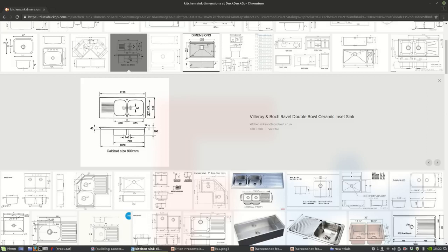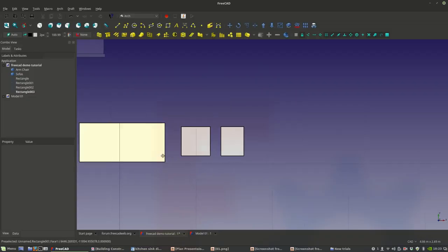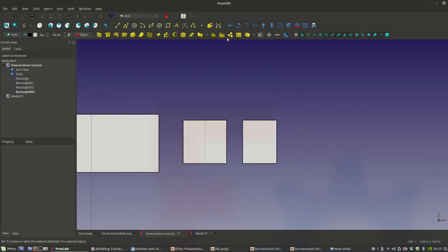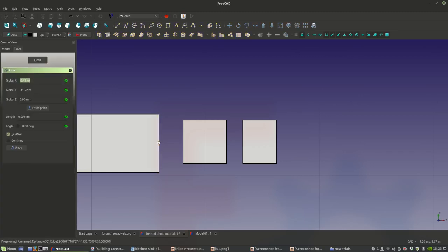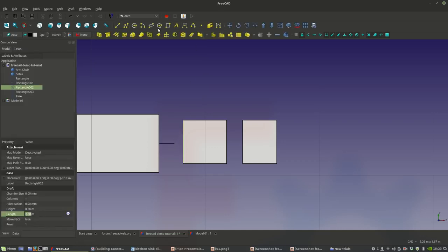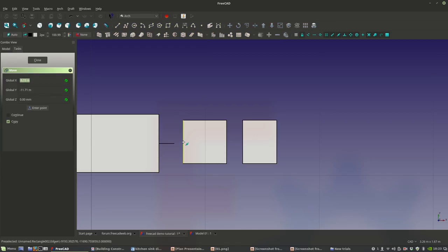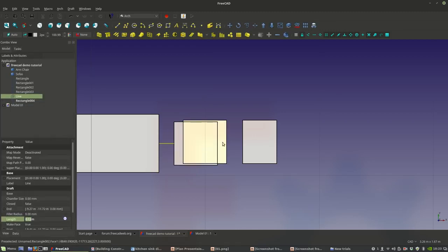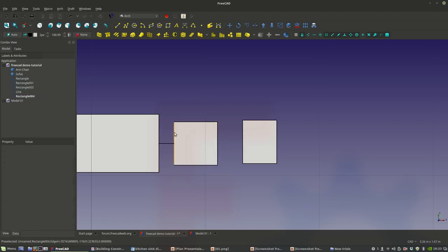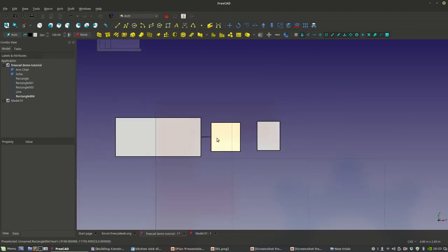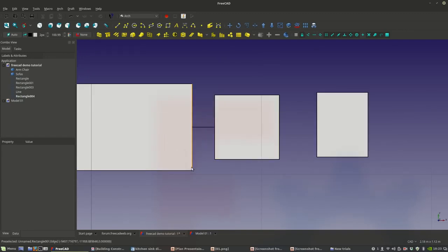And it's this little dimension in the offset. We can just be arbitrary for that one. So now maybe we want to align that with the center. So I'm going to take my align tool and then just snap at the center and just draw a small line there, and then take this guy and probably grab him at the center there and then snap him there as well. I still have the copy command, that's why I copied that, so I'm going to delete the previous copy. And then what I'm going to do now is create the offset value from the edge.